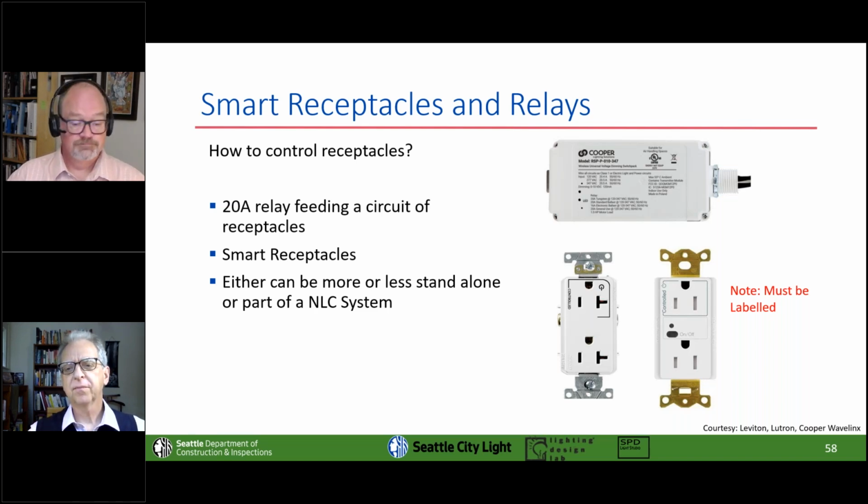And the whole reasoning here is that any little tiny load that is running 8,760 hours per year has a cumulative energy use that is often more than whatever the item is that's plugged in there that gets used for several minutes a day. So those little tiny loads from computers that are on sleep or whatever really do add up, and it's much better to have them off and cold when nobody is around.